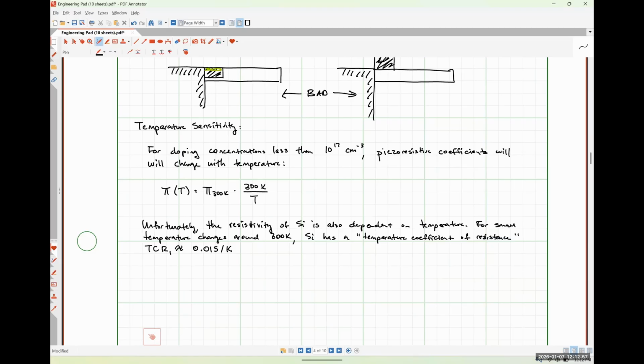So this is one of the limitations with piezoresistive sensing, where we probably would actually, and I think I'll talk about this a little bit more on Friday. Sorry, I couldn't remember what day of the week it was. So when we implement these guys and we make piezoresistive measurements, what I did here, where I had two piezo resistors in series, we might do something like that, but we would probably also have another piezo resistor set somewhere inside the anchor point where it's not going to experience any type of deformation whatsoever, right?